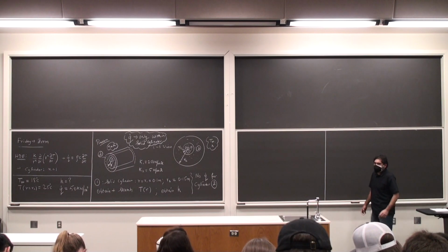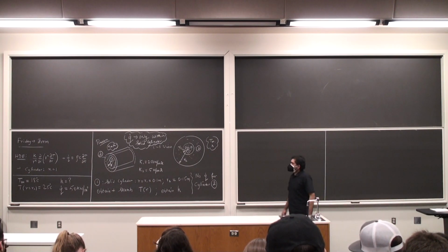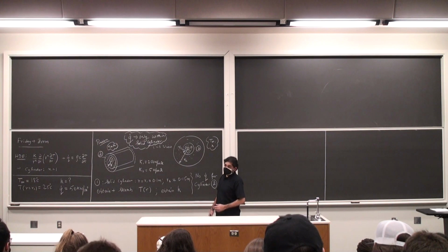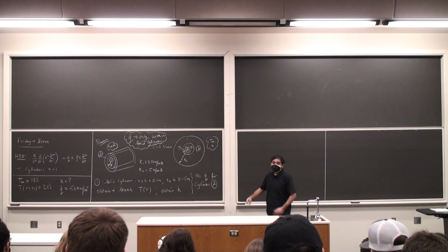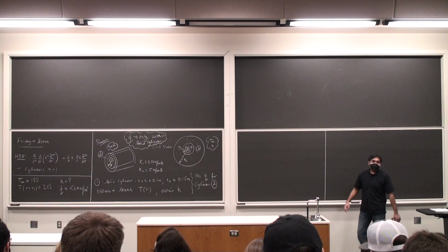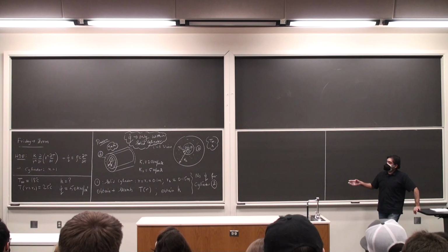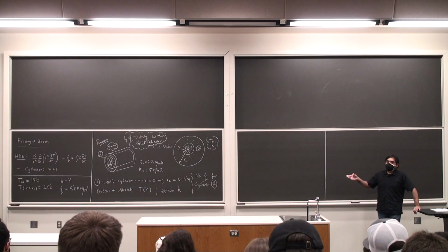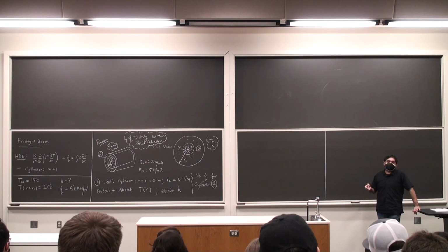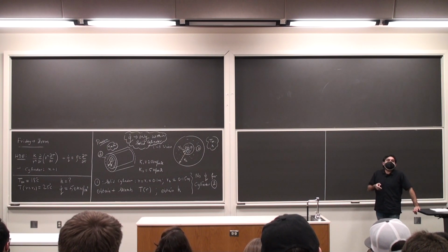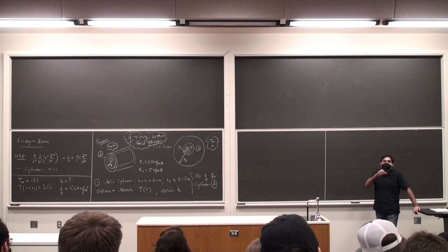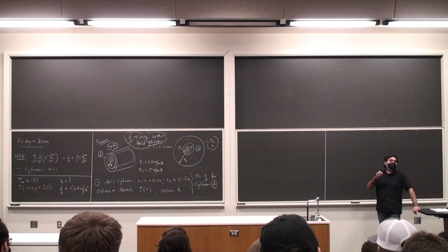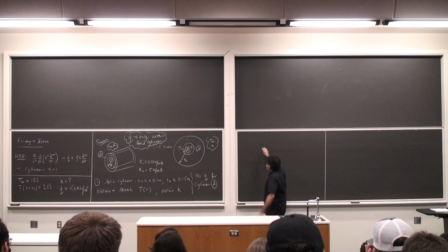So in this problem, there are certain boundary conditions that are available to us, which we need to siphon out and see how they are going to help us in solving the problem. But before I solve the problem, here is what I typically do. It's a problem on one-dimensional conduction, which means that we start off with the heat diffusion equation. I handle the solid cylinder separately. I handle the thin ring separately. I'll call the temperature profile through the solid cylinder T1 of R, and the temperature profile through the hollow ring T2 of R.